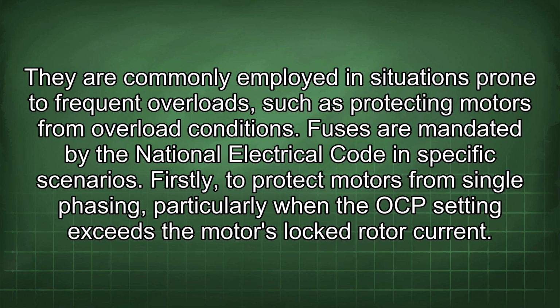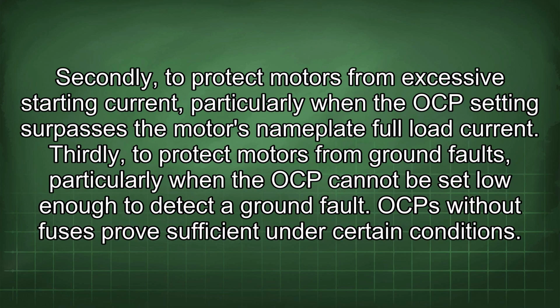Fuses are mandated by the National Electrical Code in specific scenarios. Firstly, to protect motors from single phasing, particularly when the OCP setting exceeds the motor's locked rotor current. Secondly, to protect motors from excessive starting current, particularly when the OCP setting surpasses the motor's nameplate full load current. Thirdly, to protect motors from ground faults, particularly when the OCP cannot be set low enough to detect a ground fault.